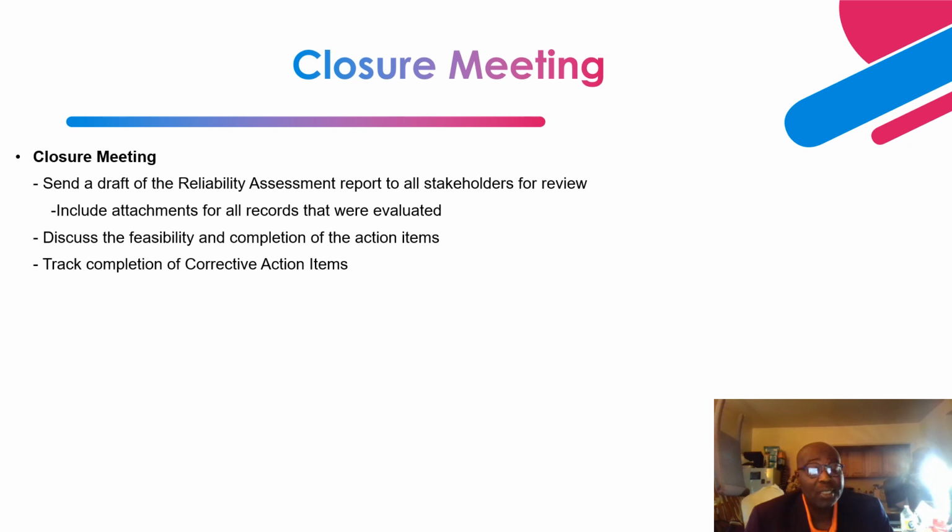Next, bushing testing results. So you evaluate the maintenance practice with basically the criteria, the capacitance C1. You determine what was measured against what is on the nameplate, and the power factor, what was measured against what it should be, which should be between 0.5 to 1%.